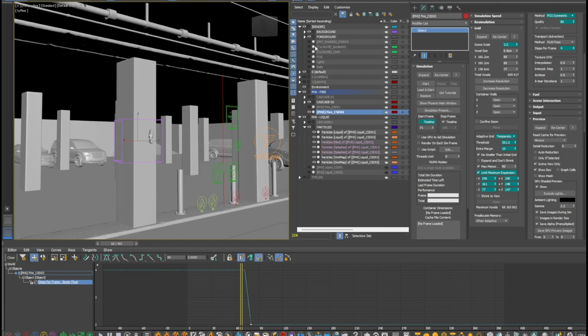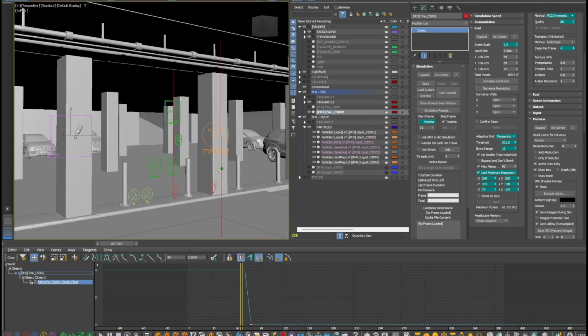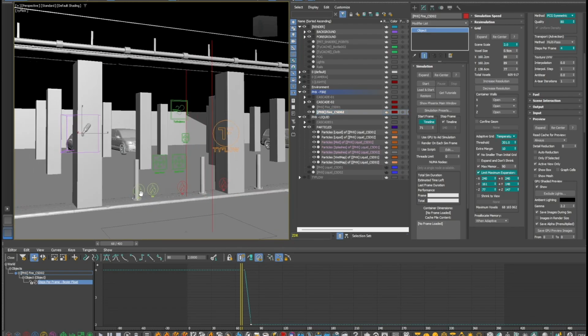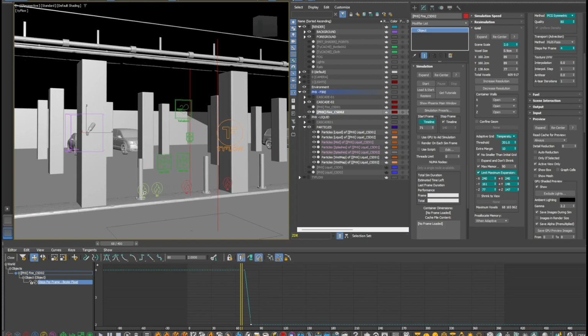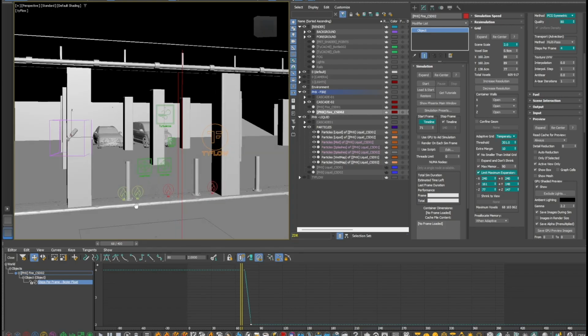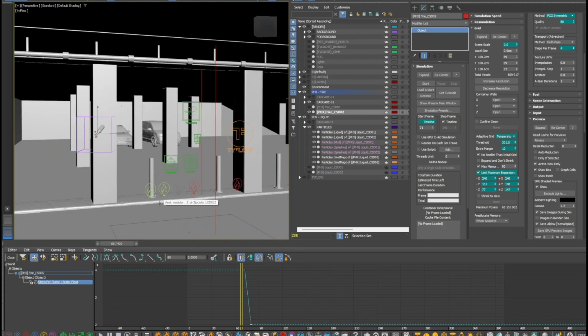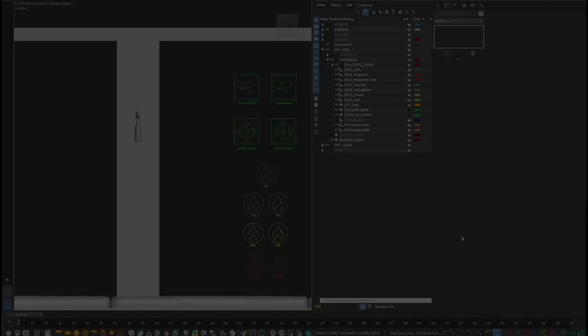Generally, it is a good practice to make your simulations inside a simplified scene and merge it into the scenes used for rendering when they are finished. But also, sometimes you may want to do a quick test render while you are tweaking the sim settings. So the Include-Exclude list is a great option to define which objects are important for the sim and prevent it from interacting with some heavy assets that perhaps have opened edges and therefore are unsuitable for simulation use.